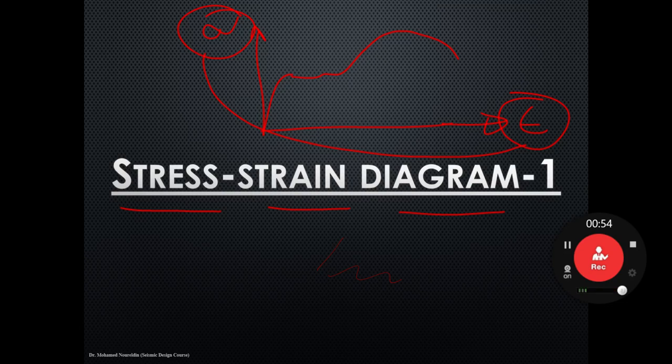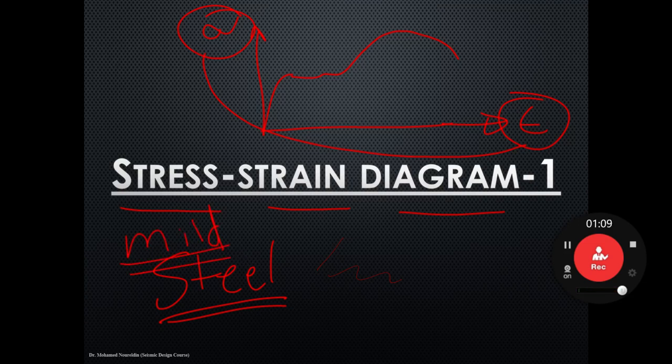stress and strain. We're going to choose one material, which is steel, especially mild steel, because mild steel makes it easy to explore all the different phases of the change between stress and strain. So we're going to find the elastic part, the yielding part, strain hardening, necking, fracture, and so on. It's very clear, and we can understand it easily.